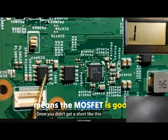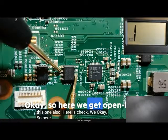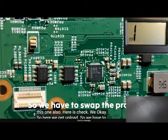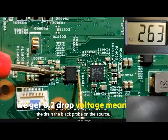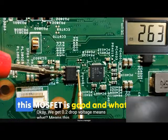The same for this one also here. Let's check. Okay, so here we get overload. So we have to swap the probes. So the red probe here on the drain, the black probe on the source. Okay, we get 0.2 drop voltage. Means what? Means this MOSFET is good.